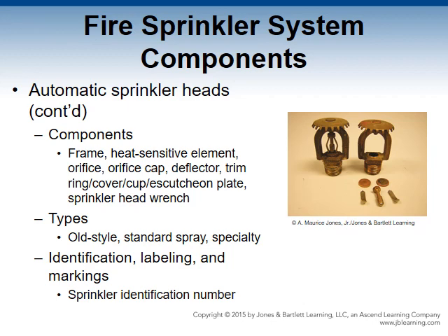Control mode specific application sprinkler heads are designed to control high challenge hazards, such as in-rack or intermediate level sprinkler heads, which provide protection within your storage racks. You have vertical sidewall sprinkler heads, which distribute water like a sidewall head, but the head installation is in a pendant or upright position. You also have attic sprinkler heads, which are installed over the peak of the attic.